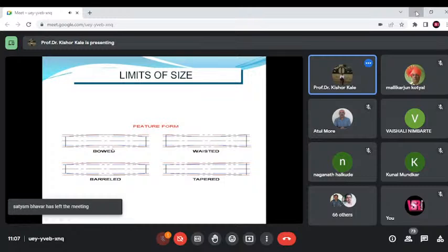But for related features, that means orientation, location, and runout, whether it is angularity, perpendicularity, parallelism, position, concentricity, symmetry, circular runout, or total runout, for all these we require two features to compare. For angularity, one surface is at 30 degrees to the other. So we require two surfaces measured, related to each other.